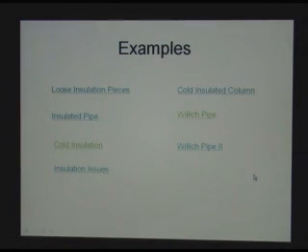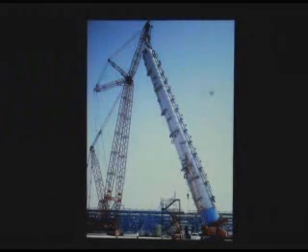Okay, the column on top right, please. This is the biggest column I got involved in insulating. I think it's 110 meters tall, 8 meters in diameter. It has cold insulation with foam glass, and it was done in the horizontal position and is now erected. The task here was to make sure the insulation stays in place during this change of position. It's worked just fine.